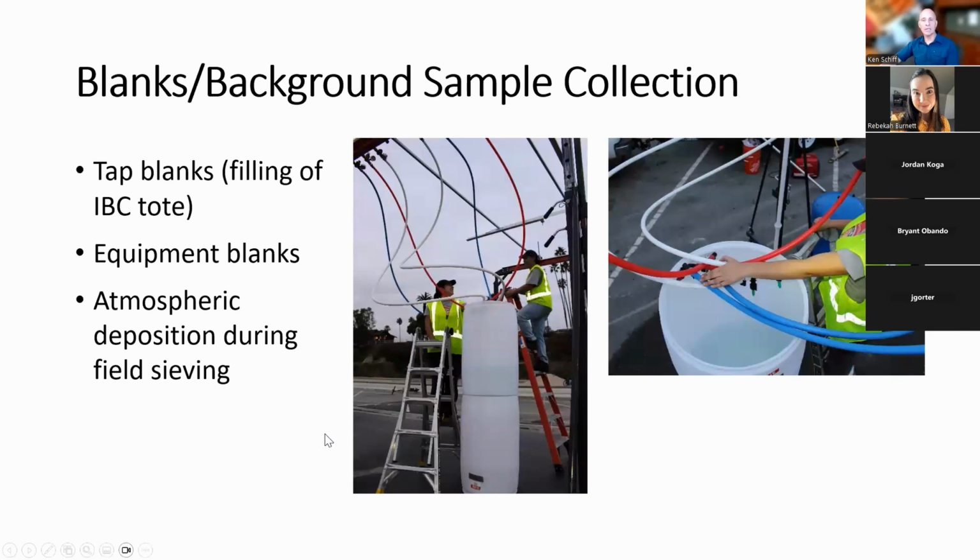The key thing to know is if you're going to do microplastic sampling, whether it's for street sweeping or anything else, you have to do a lot of blanks, because there's a ton of background contamination. We've had to spend $250,000 just building our lab to measure microplastics and prevent background contamination.